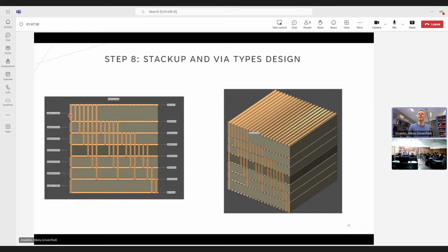This is the part of the via which is not used. And that can degrade the integrity of your signal. I will not go into details, but just remember, in the high-speed digital design, you should avoid these via stubs. Or if you want to use them, I mean, these through hole vias, you need to perform simulations, 2.5D or 3D simulations. Using, someone mentioned yesterday, ANSYS, for example.